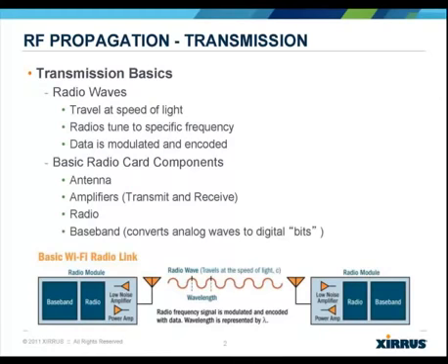RF propagation transmission. I have no intention of doing a deep dive on the properties of RF. However, we need to go over some basics of how RF propagates. Basically, the next couple of slides will discuss the positives and the negatives of what happens to the RF energy between the transmitting device and the receiving antenna. Bottom line is always start with high-quality radios. These, used with an appropriate antenna design and then measuring the RF attenuation, will determine the actual connection range and the data rates that you can expect.